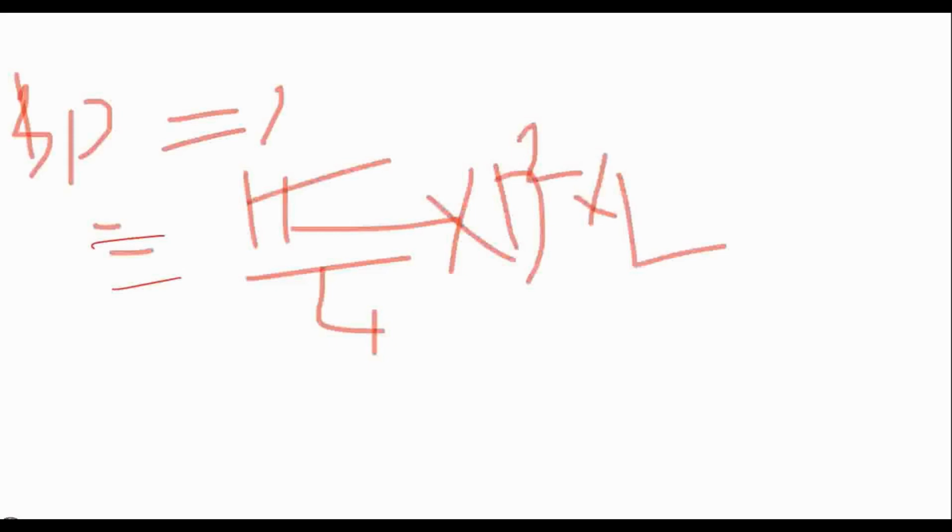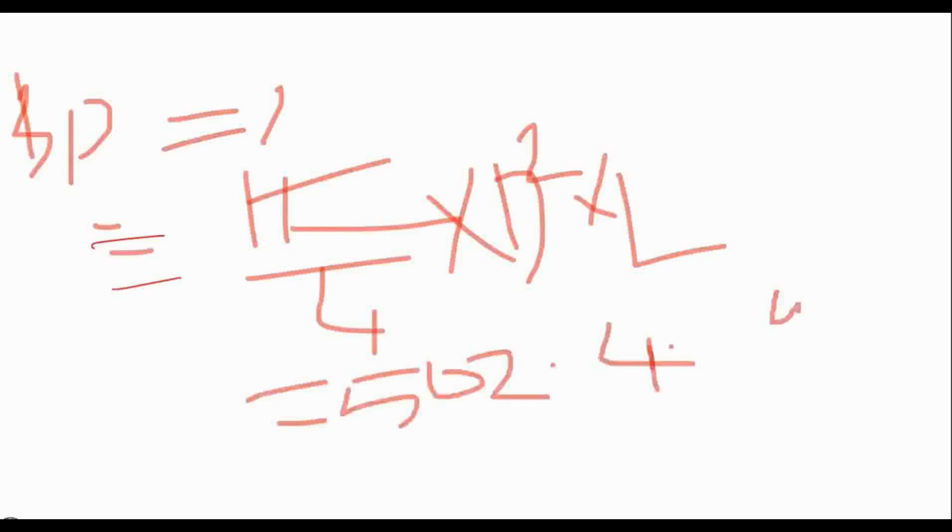Here they have given the values in terms of 80 mm, and you need to convert that in terms of meter. You also need to convert the stroke, and get the value as 502.4 cc, cubic capacity per cylinder. It's the cubic capacity per cylinder.